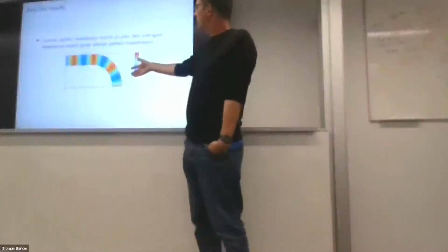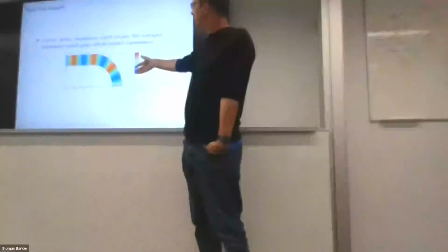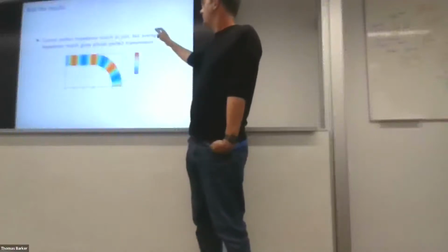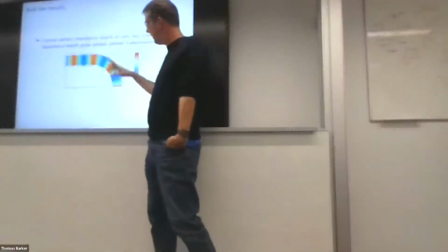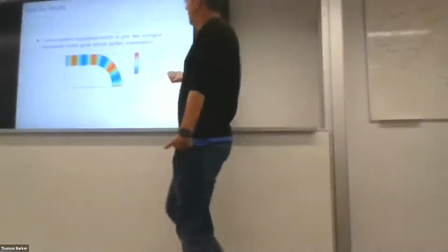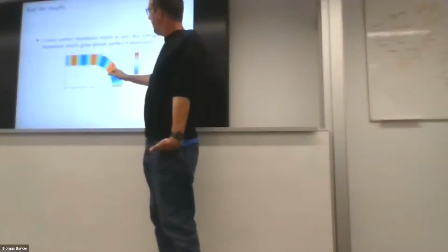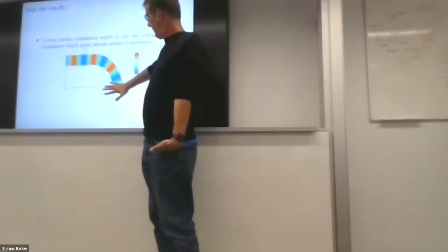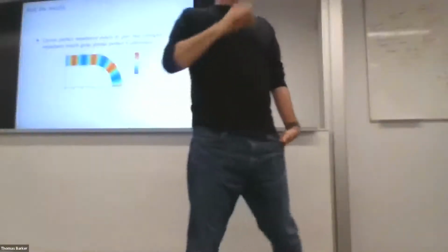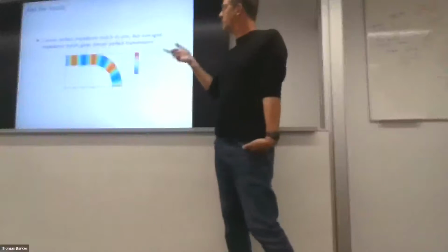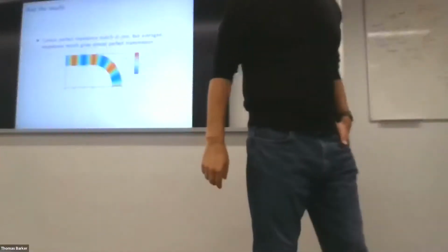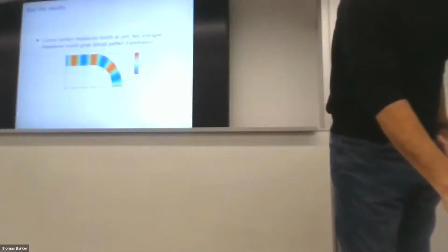Okay, so here's a diagram showing what happens when you put in one of these metamaterials. This is just a computed solution. There's a bit of a problem because you get an impedance mismatch at this boundary and this boundary. It's a very, very small impedance mismatch, so you get basically perfect transmission. Okay, if I didn't have an anisotropic bed, if I just had a flat bed, this would just be a mess. Waves would just be reflected back. This is like blowing sound down a pipe, right? You get some reflection back from the bend if you didn't have this device allowing perfect transmission.